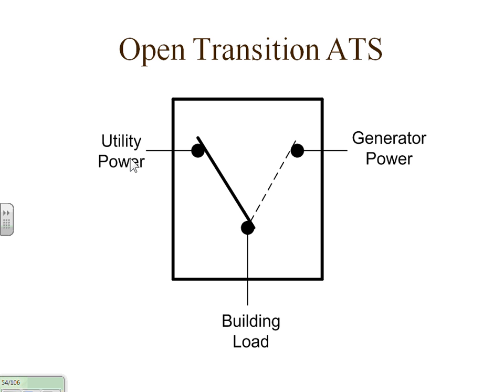And the last time delay, the fourth time delay on all transfer switches, is a function of modern technology. Most engines on engine generator sets today are designed with a turbocharger. That turbocharger runs very, very hot and very fast. And diesel engines, anytime they're loaded, they're the hottest they're going to be. And if it's a full load, they're going to be very, very hot.